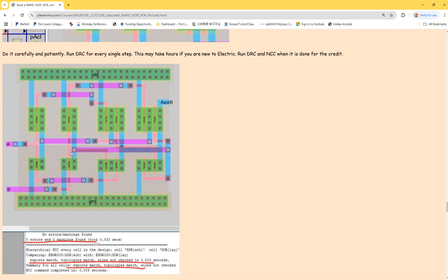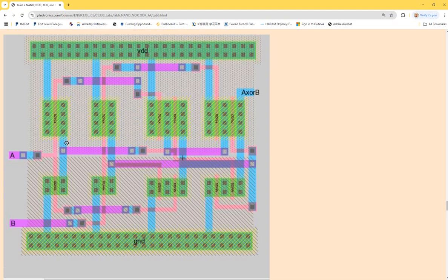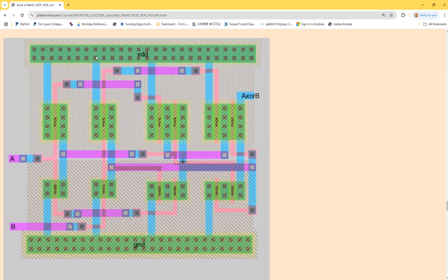Okay, let's take a look at this example. VDD are actually the taps. So these are N-tap or P-tap? Really quick question here for you guys. N-tap or P-tap? You just realize that all the power rails are just taps. It's unnecessary to create another metal wire just shorted to the VDD, right? Because all the N-taps are shorted to VDD and all P-taps are shorted to ground.